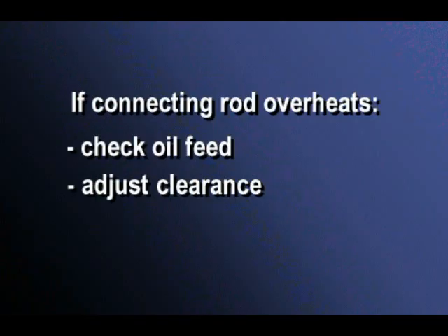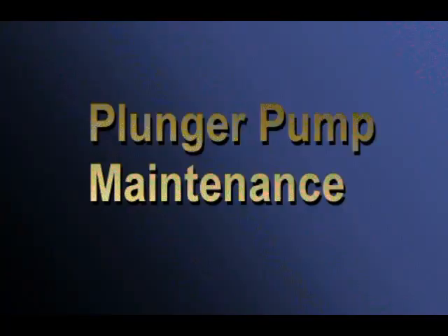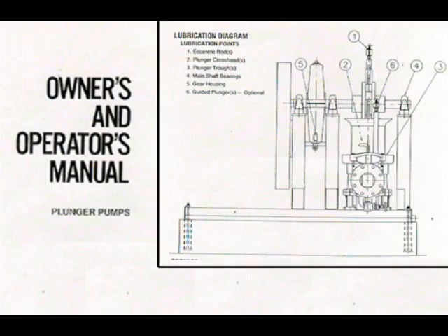Excessive clearance can be eliminated by removing shims. Maintenance of the plunger pump. Now let's spend a few minutes considering important maintenance requirements of the plunger pump. As with all equipment at the plant, the main guide to proper maintenance is the manufacturer's literature. In general, the major maintenance requirements will be in the form of pump packing and proper lubrication of the pump.